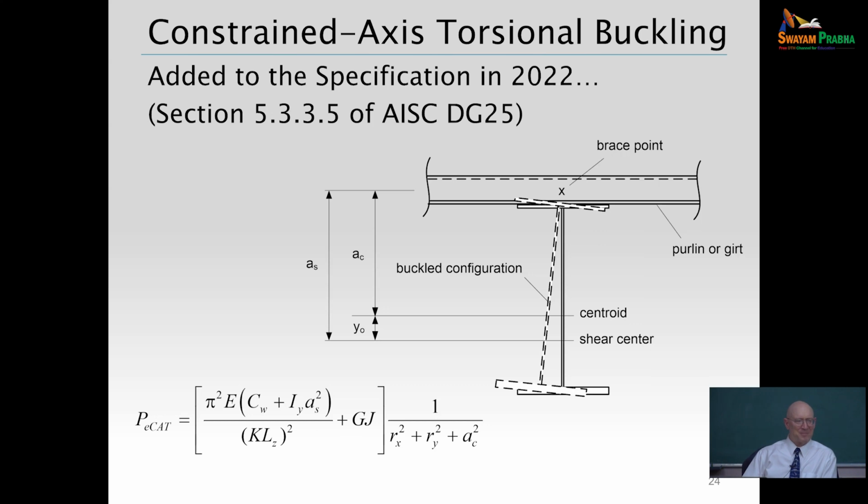I was always curious about that detail I noticed in some places, because they weren't really bracing the compression flange. Correct. If that's framed in reasonably close to the compression flange, then it's probably pretty good. Okay, thank you. What would be the unbraced length in this torsional buckling?